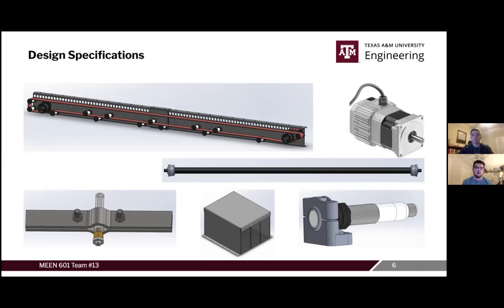In the bottom left, we have our nozzle assemblies. These come out at a 43-degree spray angle. We have 6 of these placed throughout the spray chamber. That spray chamber you find there in the bottom center is made out of sheet metal with PVC shielding to help reduce the weight, and again keep a lot of the spray disinfectant contained within the chamber. And then in the bottom right, we have our proximity sensor. This is a photoelectric sensor that will detect when an item is entering the chamber in order to turn on the spray system to mitigate any excessive use of power.